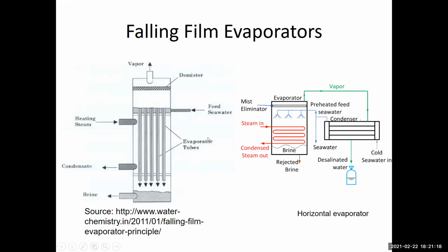Yeah, here we're talking about that's the difference. This is the one that we are using, and actually some people said, why should we make the tubes horizontal like this? Why don't we make them just vertical? And vertical tubes is going to have a problem because if this is the tube, the boundary layer is very thin here at the leading edge, and then as the thickness of the boundary layer increases, the value of h decreases.